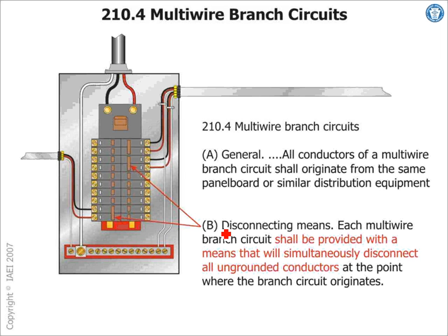As we all know, guys, if you have a multi-wire branch circuit, they have to be identified. That came in 2008. Can you see how they group? They have to be grouped together, tied together, unless identification is clear. Would you be in doubt that this neutral is shared between these 2 hots? It's very clear, so you don't have to wrap them together.